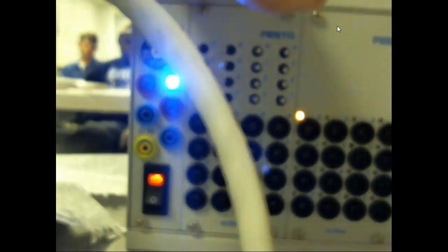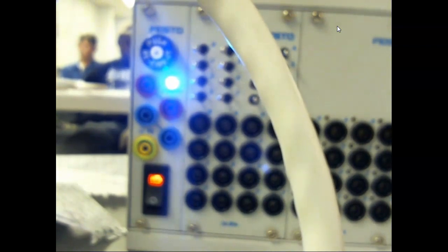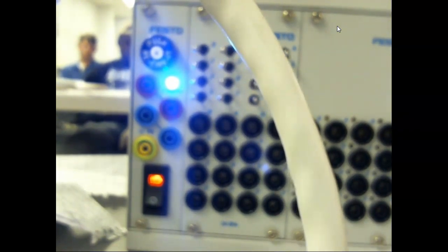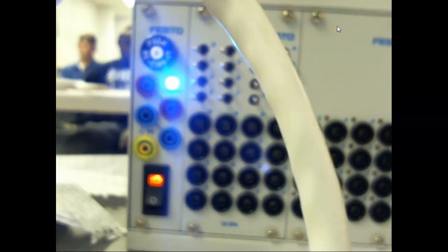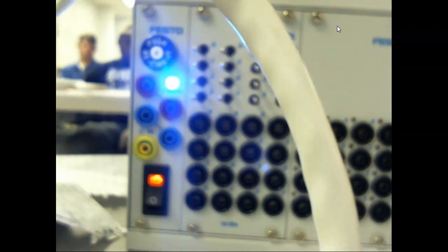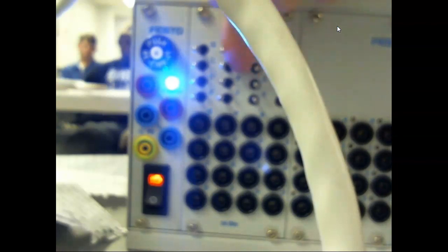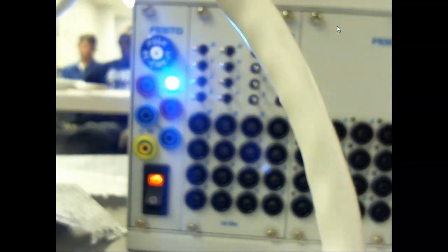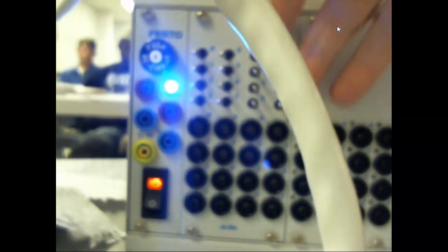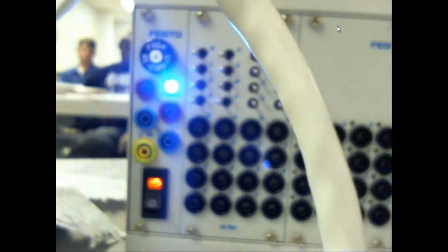But this is not the trainer. This is the mount for the PLC. I'm sorry. So this PLC does not have 16 inputs, and it does not have 16 outputs. How many inputs did I say? 10, and how many outputs? 6. Okay. So one of the labs you're going to do, when you get assigned to a station, is say how many inputs your PLC has and how many outputs it has, and somebody's going to put 16, right? Because they're not looking at the PLC, they're looking at the mount for the PLC. And you can buy more than these. If I had 32, then I could buy another one of these panels and then have the cables to actually wire it up.